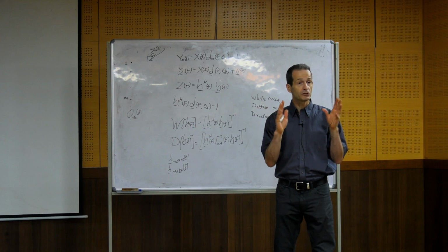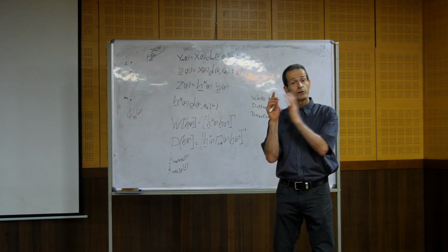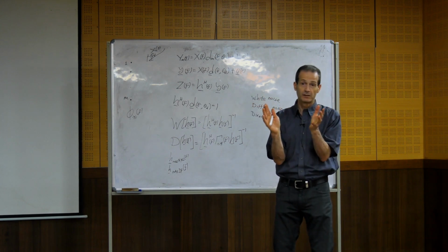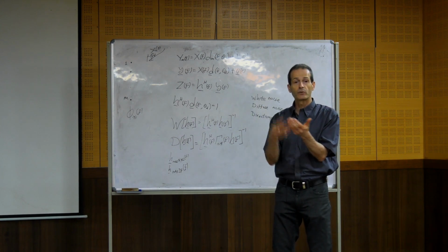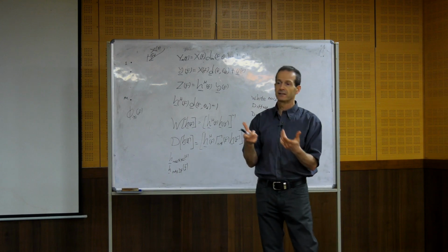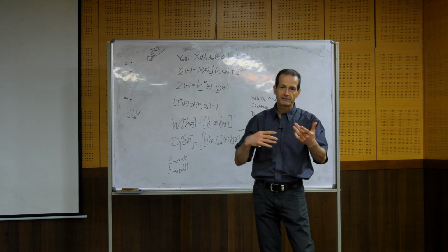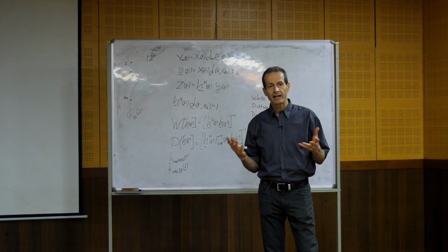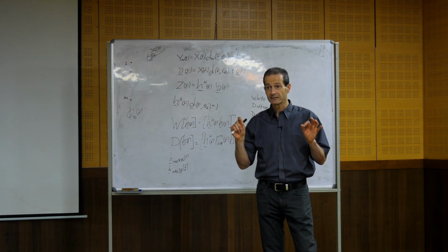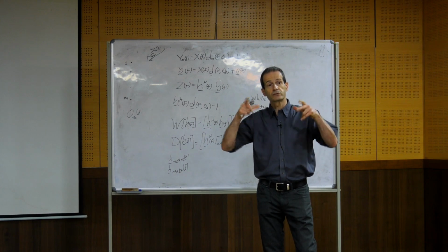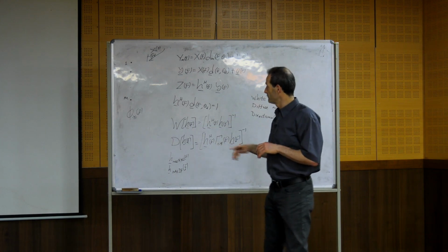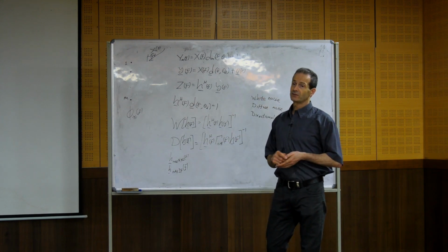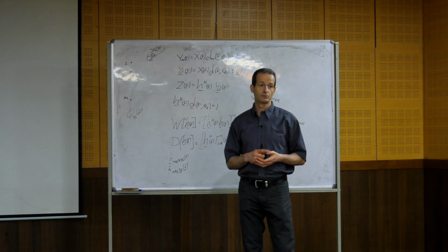Okay, so for each device we make these measurements, and then we design the beamformer and the rest of the processing algorithms. Howling control, the feedback suppression, all that. We design all that based on the measurements, and we need to put the exact beamformer and algorithms for each device. It will be different. So this is something that is very expensive to do.